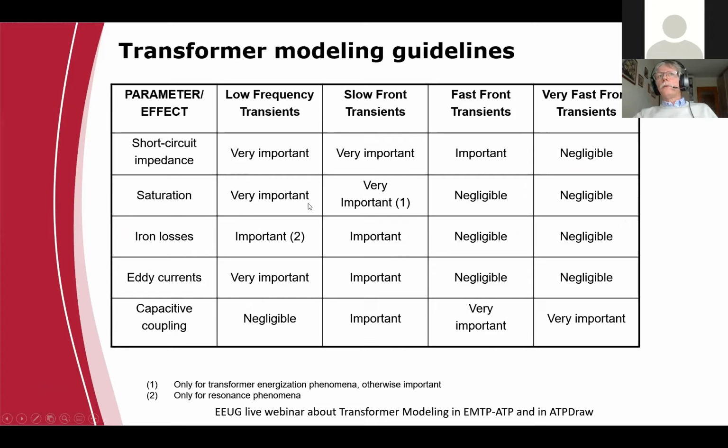Iron core losses is also important. Eddy current is also important. So if we are dealing with these low frequency range studies, the first 4 factors, the short circuit impedance, the no load losses, the no load current, eddy current losses are important.